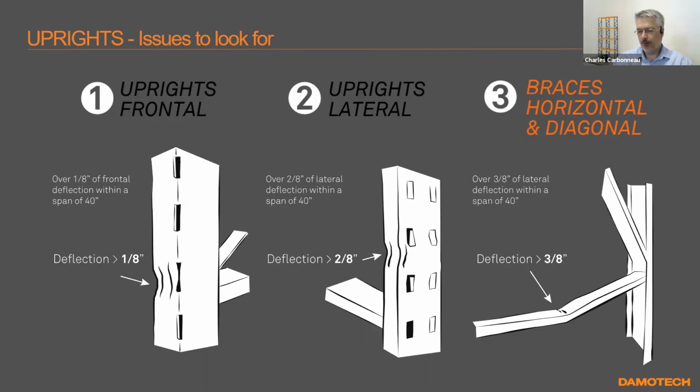If you're above a 1/4 inch, you're entering that gray zone. If you're beyond 1/2 inch of deformation, that's it. That's replace the column. For a brace, we tolerate a little bit more. That would be in non-seismic zones. Of course, if you're in a high seismic zone,